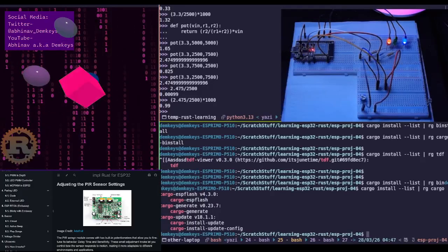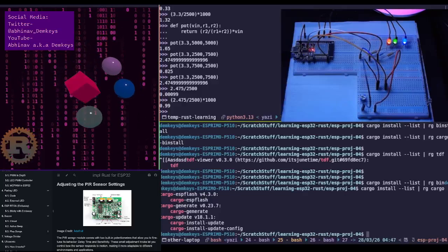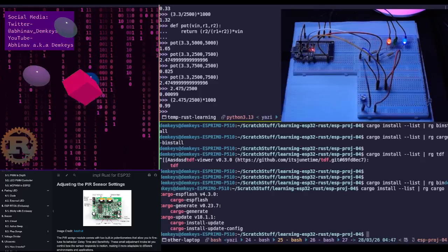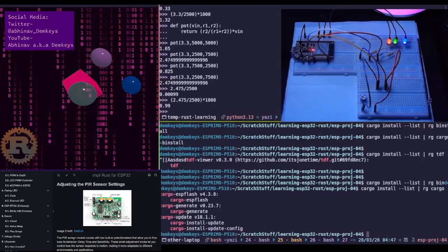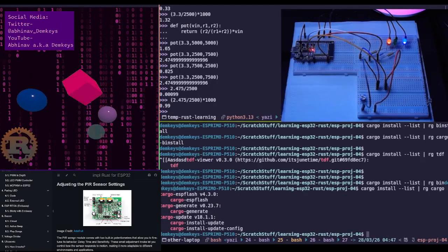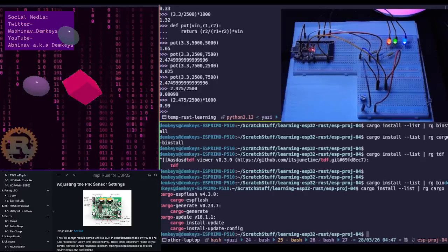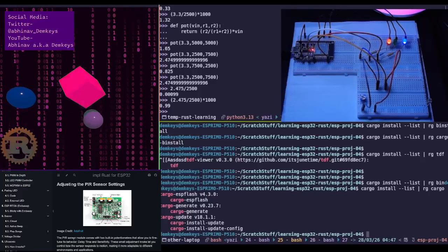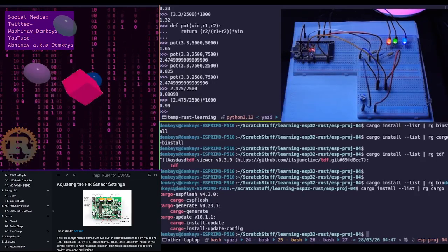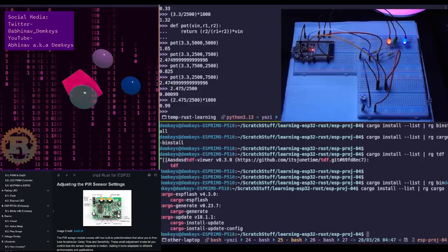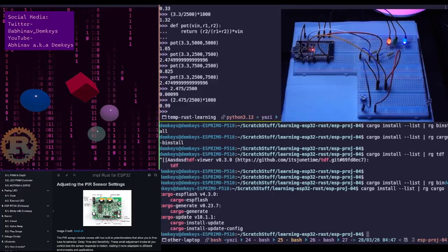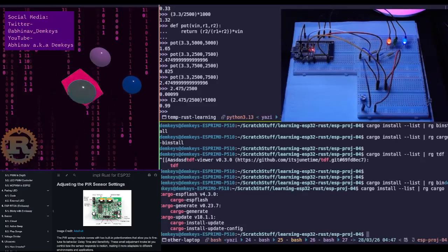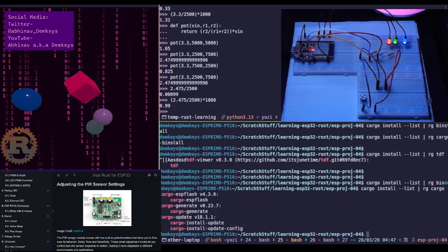What else is there? There's more stuff. There's a servo motor in there. I believe that's meant to connect directly to the microcontroller. It's worth mentioning that these are projects that are meant to be done with Arduino Uno, which works in the 5 volt range. I don't know what the max current supported there is, but it's working in the 5 volt range, while the ESP32 usually works in the 3.3 volt range.